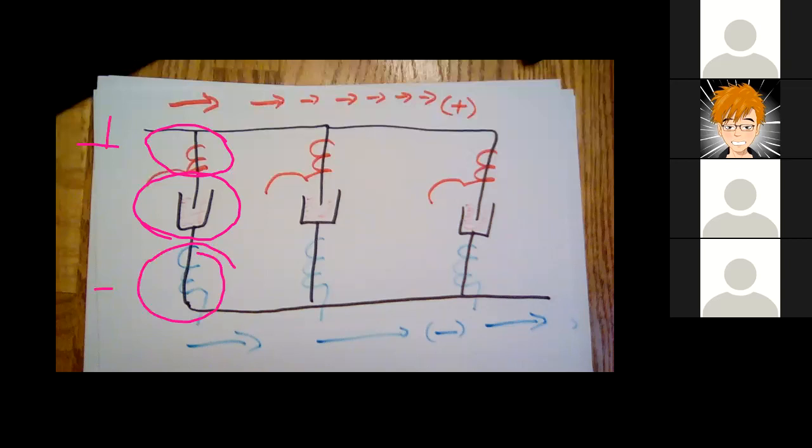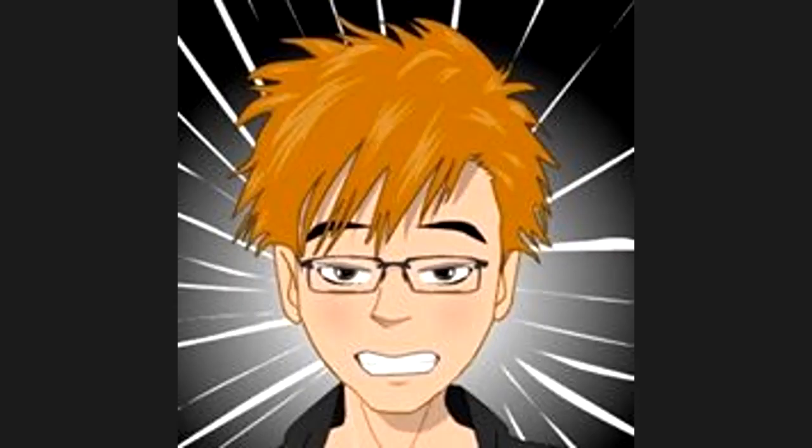And so that difference, if we wanted to harvest off of this circuit, could be done by bypassing the capacitor and setting up something that had resistance, like an LED or a motor, and you may have to put another resistor on the discharge end, to make certain that it didn't empty all the capacitors at once. Just one of those kind of interesting ideas, observation of the circuit. We'll end that one and pick up our next picture.